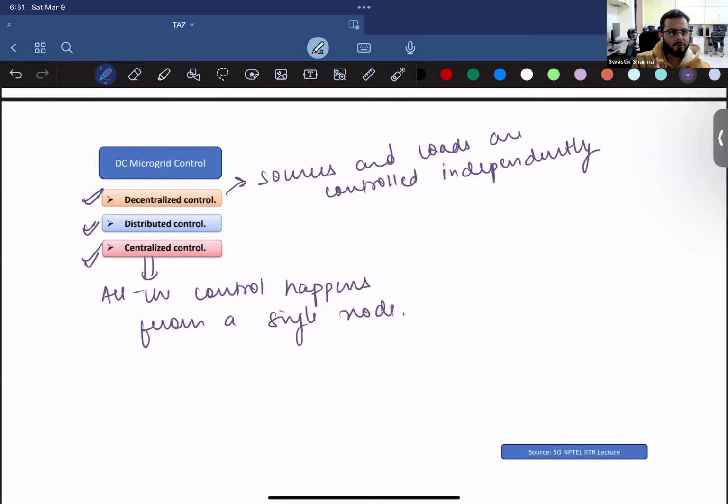So changing one will produce a change in two quantities. Earlier there was only one change. Active power changed, frequency changed. Frequency changed, active power changed. If voltage changed, your reactive power changed, or if reactive power changed, your voltage changed. But now both of these quantities are dependent on both frequency and voltage. So how will you produce an effect?